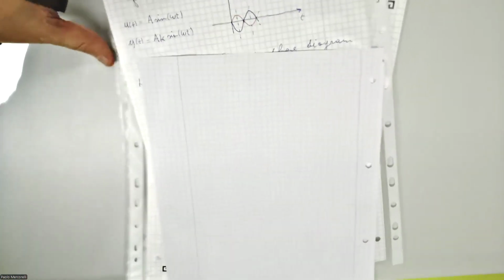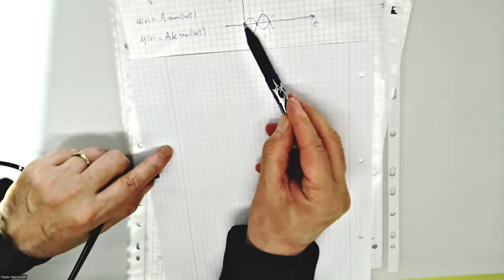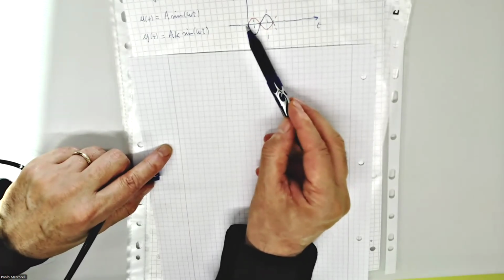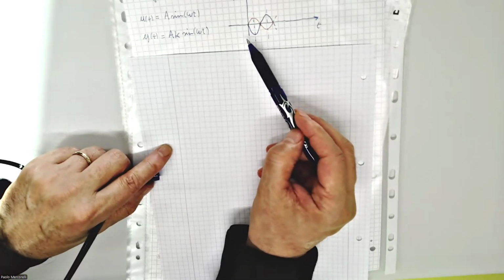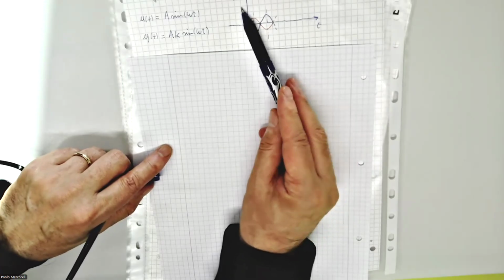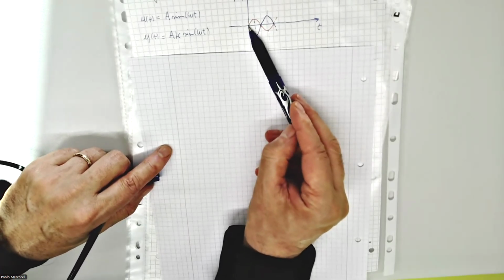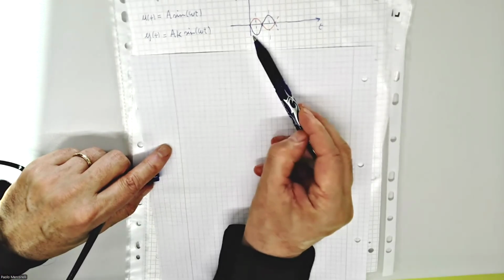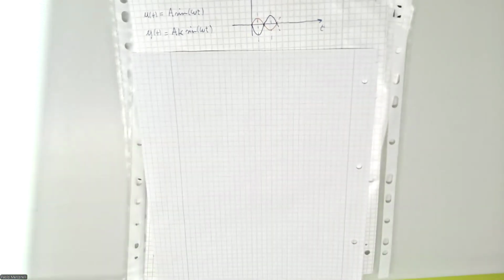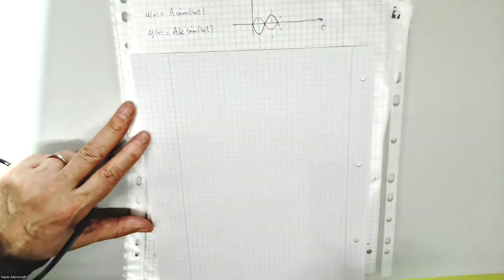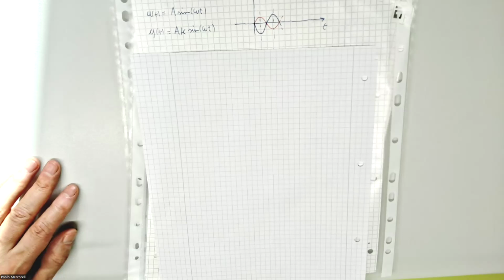Just to go more in depth. As I told you, I have here something. If k is negative, it happens something like that. We have the same u, I mean, assuming u equals sine of omega t. The output y is not as before, k multiplies sine of omega t, but is minus k multiplies sine of omega t. Therefore, this is minus 180 degrees, because the signal red with respect to blue, the difference in phase is 180 degrees.